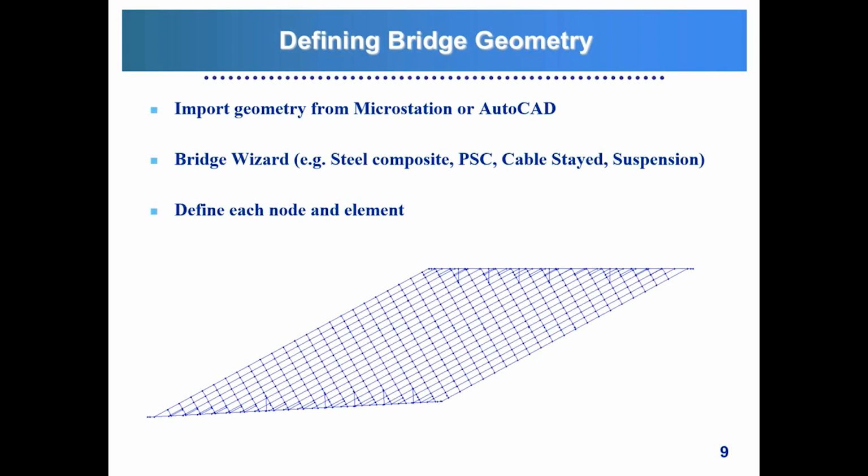The other option that MIDAS provides for the definition of the geometry is to define the actual geometry inside MIDAS, and in that case you will need to define the nodes within MIDAS and then connect those nodes with your elements.